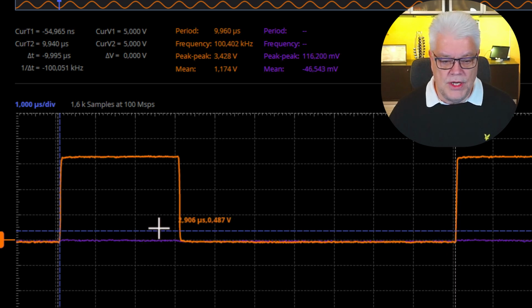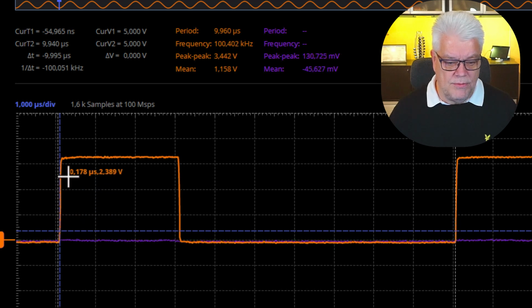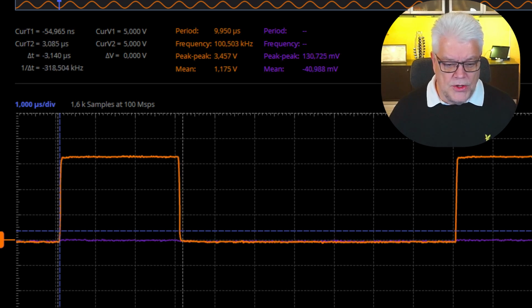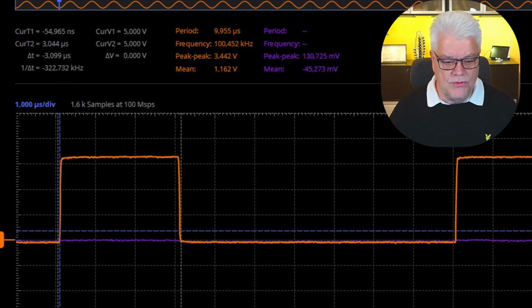So here in between, we now expect to have 3 microseconds between this upgoing flank to the downgoing flank, and we can measure that by moving this cursor to this flank approximately. It's very hard to get it exactly, but close to it. And we can see that there is a delta of 3 microseconds between the first cursor and the second cursor. So that means that that is correct. That is 30% high and 70% low.